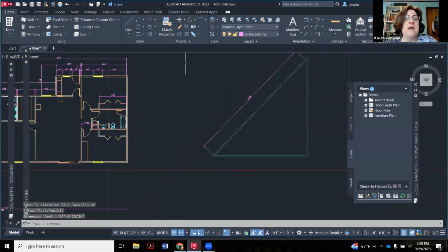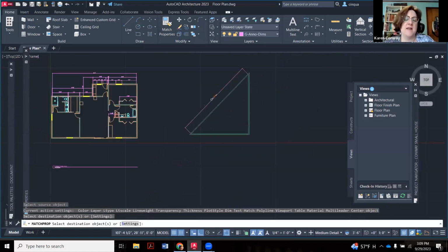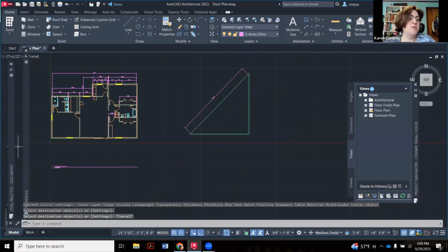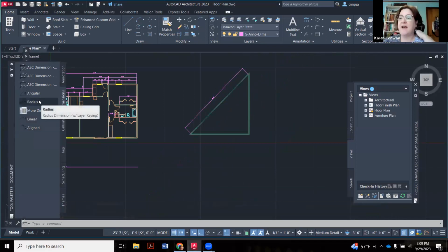Again, now it's not the crazy math. So we're going to click on Match Properties, click on the ones over here that are already rounded to a 1/2 inch, click on it, and now there's your number. So most of you are only going to need those two. There's a couple other options in terms of measuring circles and things like that, like the radii of curves. I don't think anybody has that in their first project, but again, that one's not too hard.